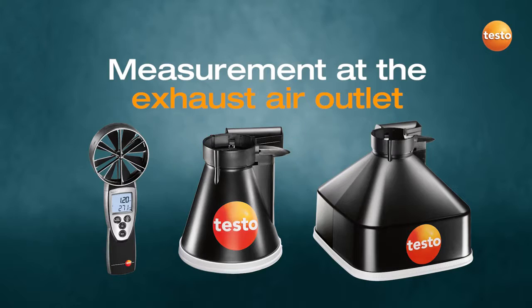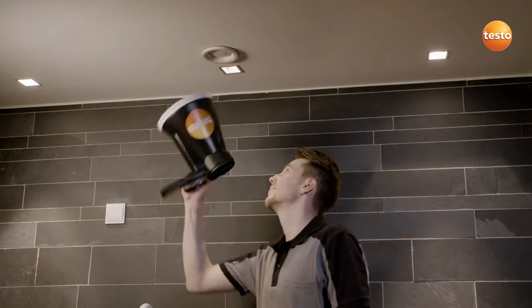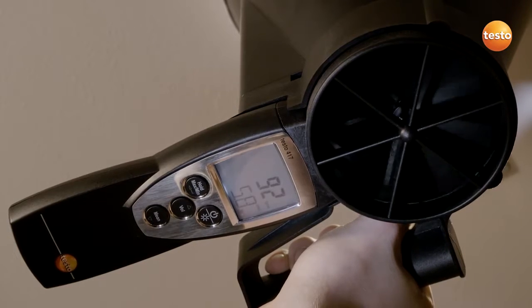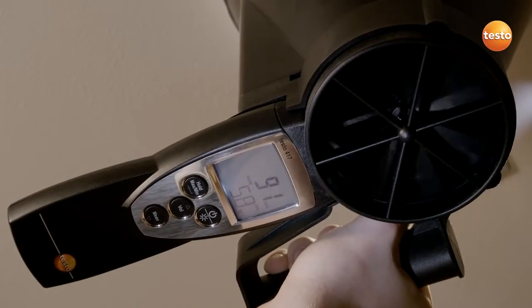This is how you measure properly at the exhaust air outlet. A funnel is required to measure the exhaust air. The reason? There is no directed flow profile available for exhaust air as the air is sucked in funnel-like from the room. This means there is no definable area in the room via which the volume flow can be determined. This challenge is easily solved with the aid of the Testo 417 funnel. This is because the funnel creates defined flow conditions at some distance from the plate outlet in a fixed cross-section.